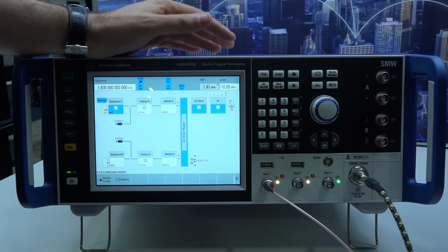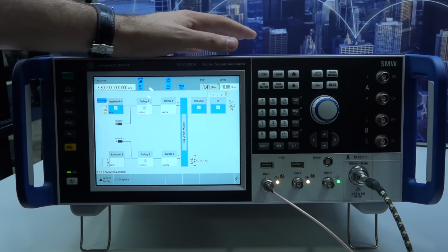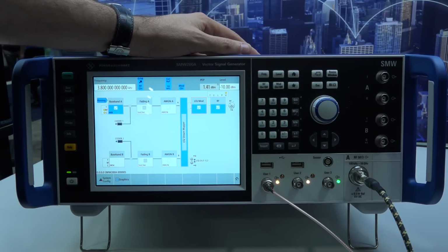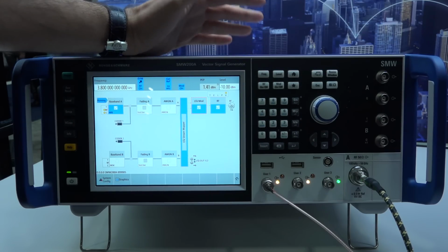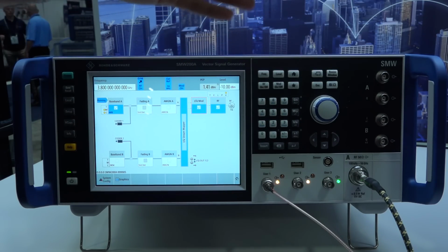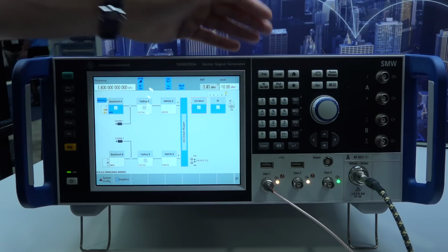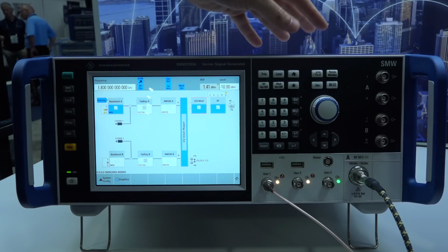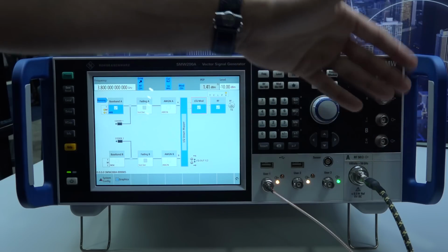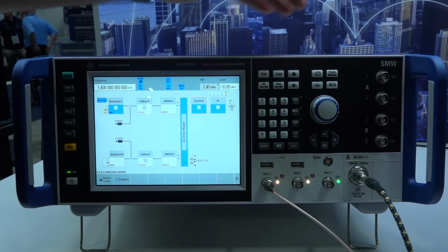But it also has not only all of its frequency calibration characterization, which is typical for synthesizers, but it also has its nonlinearity coefficients factory calibrated inside the unit. So what this means is now you can push this to higher output powers across all of its frequency range and output power, because it will apply the DPD algorithms directly inside the unit. So what comes out has that already embedded inside because it's been pre-calibrated.